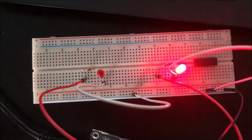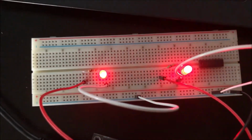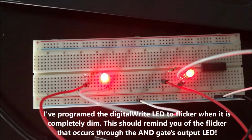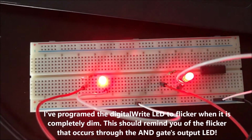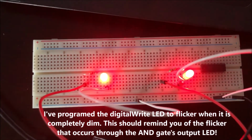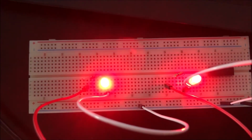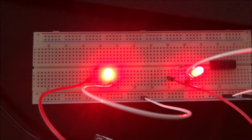To show you how the AND gate works in conjunction with this, I've disassembled it and made it so both of these LEDs are lit. So what you're seeing happening is the digitalWrite LED is going through its cycle fairly quickly. Every time it completes one step in its cycle, the analogWrite LED on the left enters its next step, so it has gradually gotten brighter.